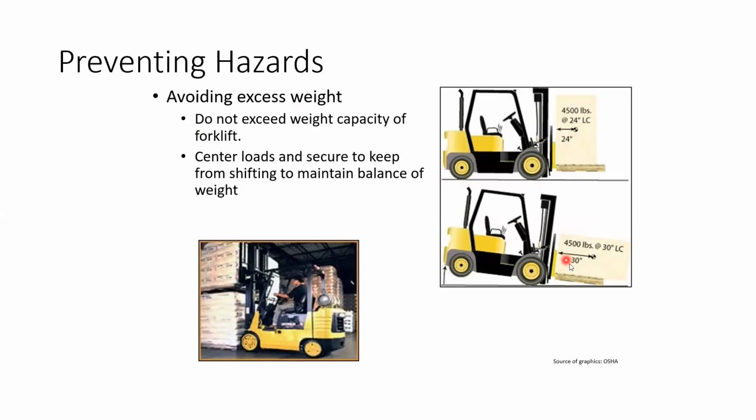Avoiding excess weight, as you see here. This weight is excess, more than the forklift arms can take. Okay, don't exceed the weight capacity of the forklift. Center the loads and secure them to keep them from shifting, to maintain the balance of the weight. Okay.